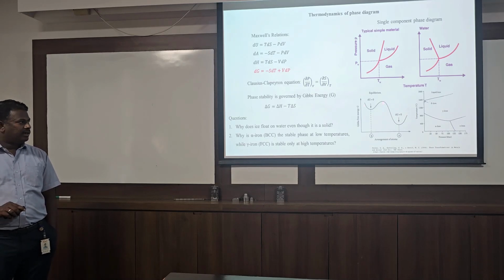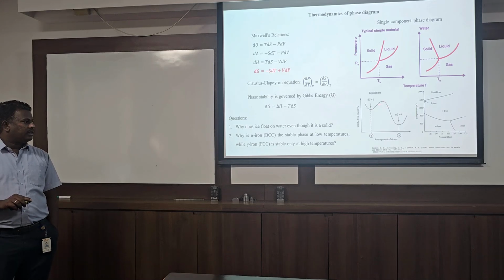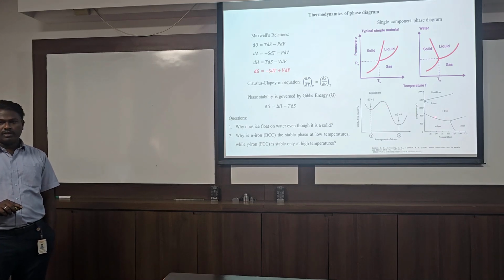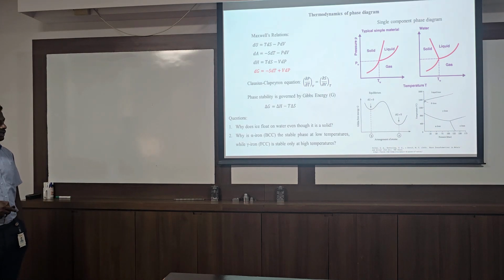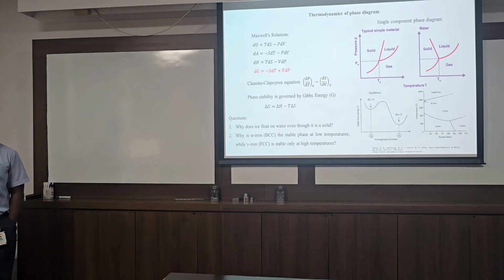So if it is higher energy, what will happen? It will try to reduce the difference, and this is the driving force. If you provide any kinetic energy or thermal energy, the atoms will cross this barrier from this to this, and come to this position. So always nature will go to the lowest free energy. That is the natural principle. Even in phases, solid, liquid, and within the solid there are a number of phases. Out of those phases, whichever has the minimum energy is more stable. That is how thermodynamic predictions are done.